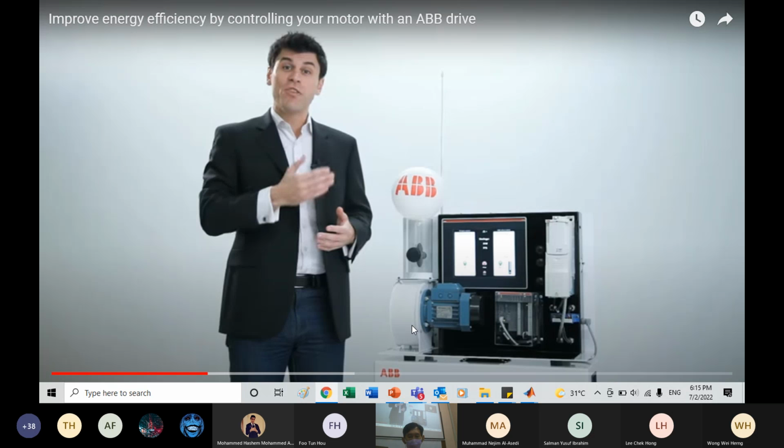You see, this is a motor, and there is a fan. This motor produces a wind blow. It puts a balloon here. If you want to control the balloon at a certain height, right? In the old days, even including many of the buildings I saw before in some of my consultation work, we are still using this system. Even big shopping malls, the aircon blowing is actually using what we call a mechanical valve. That means the motor is 100% on, but if it's too cold they use the valve to control it. So this is what happened.